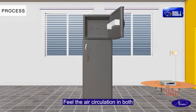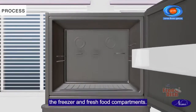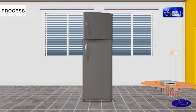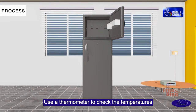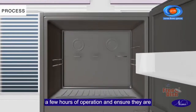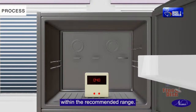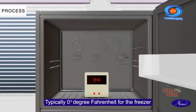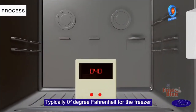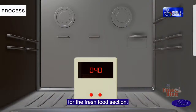Feel the air circulation in both the freezer and fresh food compartments. The air should be cool and consistent. Use a thermometer to check the temperatures in different compartments after a few hours of operation and ensure they are within the recommended range. Typically 0 degrees Fahrenheit for the freezer and around 37 to 40 degrees Fahrenheit for the fresh food section.